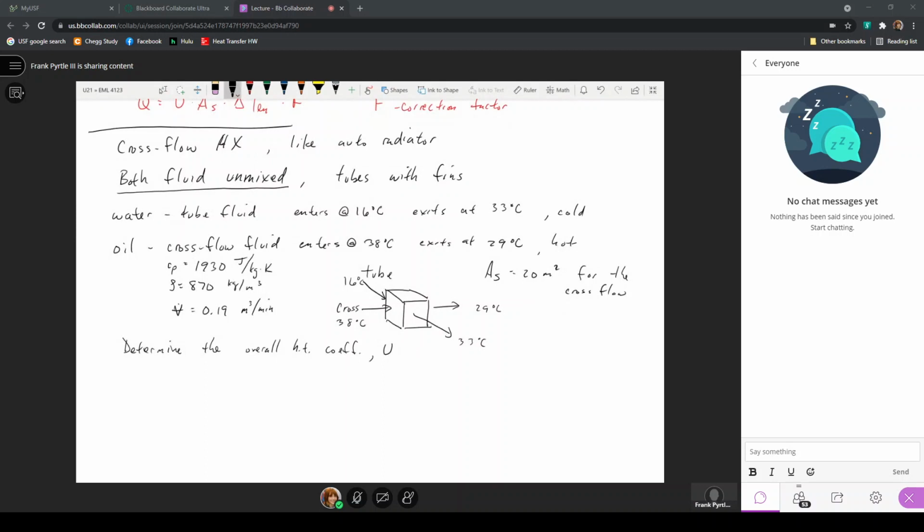The heat transfer out of the hot fluid is the capacity rate of the hot fluid times T hot in minus T hot out. The heat transfer rate into the cold fluid is the capacity rate of the cold fluid times T cold out minus T cold in here. So when I'm writing those expressions, this allows me to consider, well, first, what is the heat transfer rate?